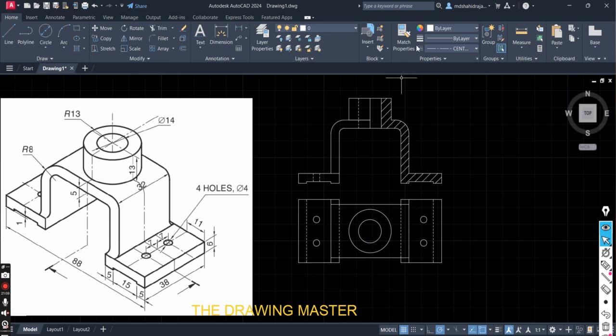Delete this. Select this line again. Start the cutting plane here. Go through this full hole. Take a 90-degree turn up to the center. Now you can take a turn from here to enter into the center of the hole. Check this cutting plane now.